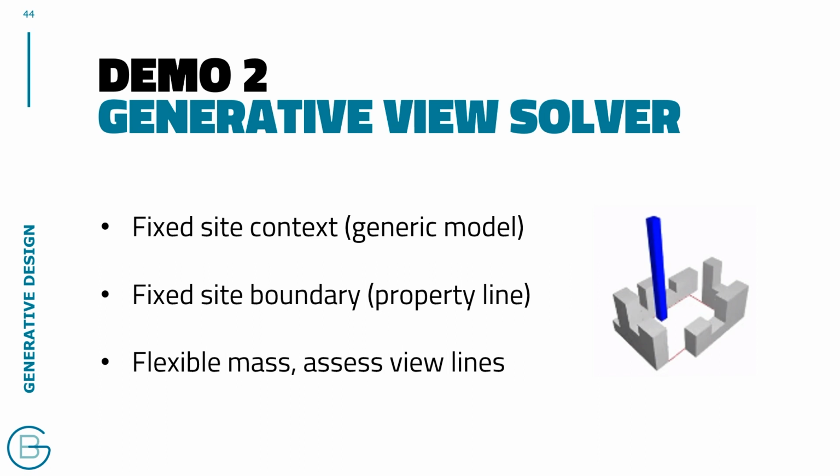So you might want to mix and match with other types of things, such as dividing the floor plate using a very simple division algorithm to determine how many apartments you can get on each floor, and maybe you'll have a threshold where you need no less than, say, 6 on a floor. There might be some limit that limits what you can actually accept as a good result. In this case, I've worked quite simply and just focused on giving the building a fair amount of free rein and giving it a position on the site randomly, and then measuring the amount of views I can achieve.